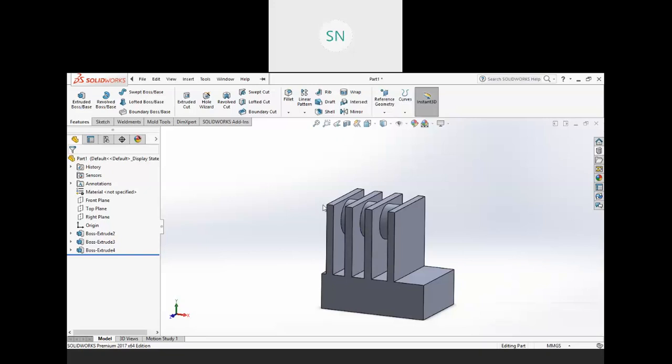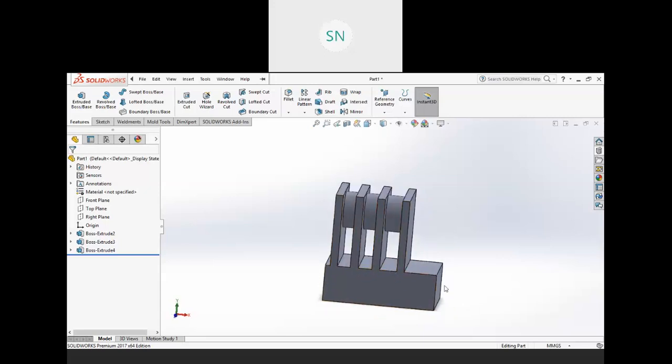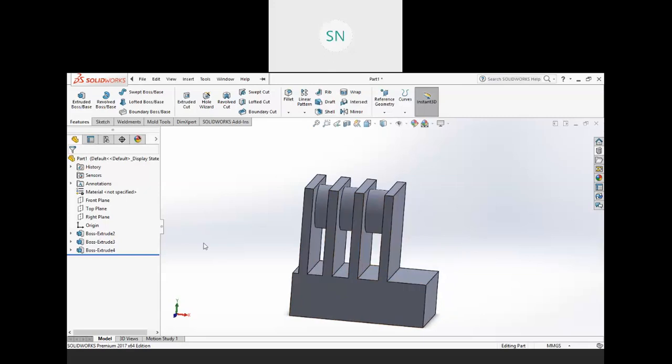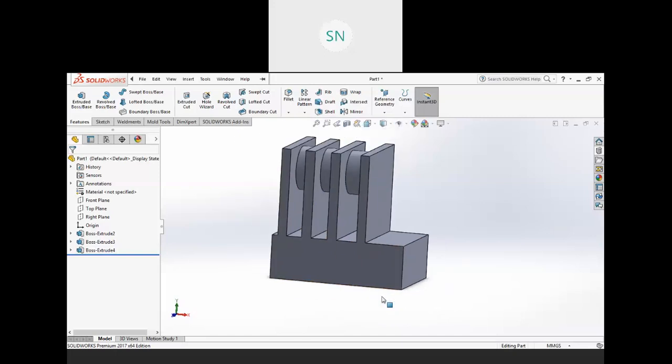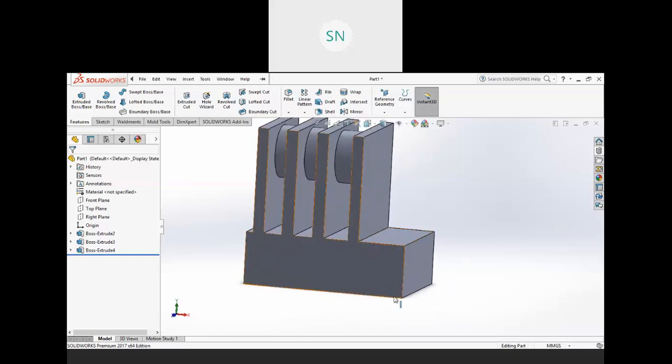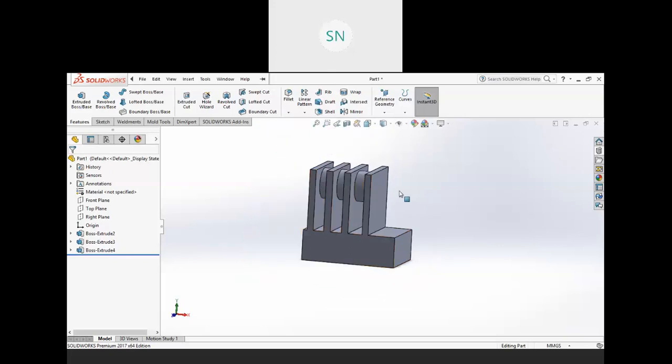Now see, as you all know, in our last extrusion, we have created an underdefined sketch, right? So as you all know, this is a parametric modeling software. That means we have created 3 extrusion operations over here, and all 3 are listed over here. See, and somehow, for example, I have decided to change this thickness. Instead of this 50 mm, I just want 15 mm. By mistake I entered 50. So we can easily edit that.